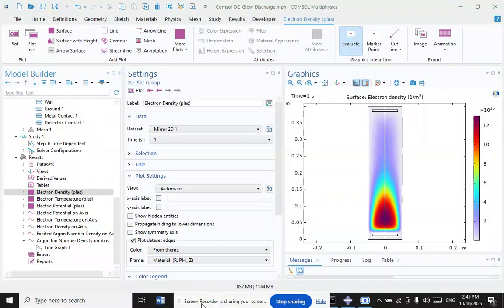And what about electrical conduction in gas? Voltage-current characteristics of electrical discharge in neon at one torr with two planar electrodes separated by 50 centimeters. A. Random pulses by cosmic radiation. B. Saturation current. C. Avalanche Townsend discharge. D. Self-sustained Townsend discharge. E. Unstable region, corona discharge. F. Subnormal glow discharge. G. Normal glow discharge. H. Abnormal glow discharge. I. Unstable region, glow-arc transition. J and K. Electric arc.